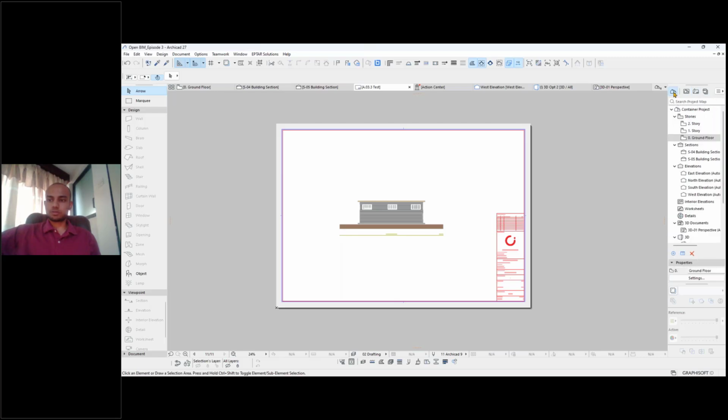First I was in the project map. I took it towards the view map. From the view map, we created this layout here. And then finally we will head down to publisher sets. For the publisher sets, we have already created a folder that represents floor plans, elevations, and sections. And in these, we have kept the saved floor plans, elevations, and sections layouts, right?